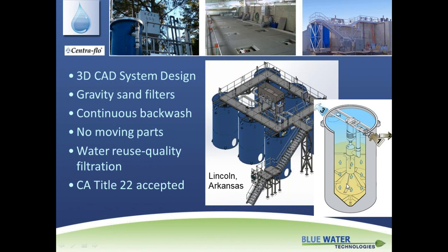So you get a countercurrent flow with the media flowing downward, water flowing upward. And the water used for the backwash is actually internal to this vessel. So again, limited moving parts. There's just a portion of the clean water that flows up through the bottom portion of, you can think of this as a cylinder, countercurrent to the media as it's falling, so that'll carry away the contaminants out of a backwash stream. So that's how the physical system works.